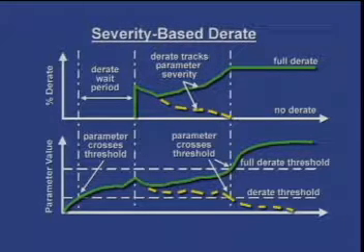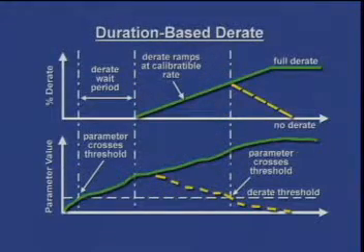An engine protection condition is determined either based on the severity of the reading or the duration of a reading. A severity-based out-of-range condition compares the current reading to a predetermined threshold or range. The parameter is out of range when it exceeds this threshold. A duration-based out-of-range condition initiates engine protection when a predefined condition exists for a predetermined time.